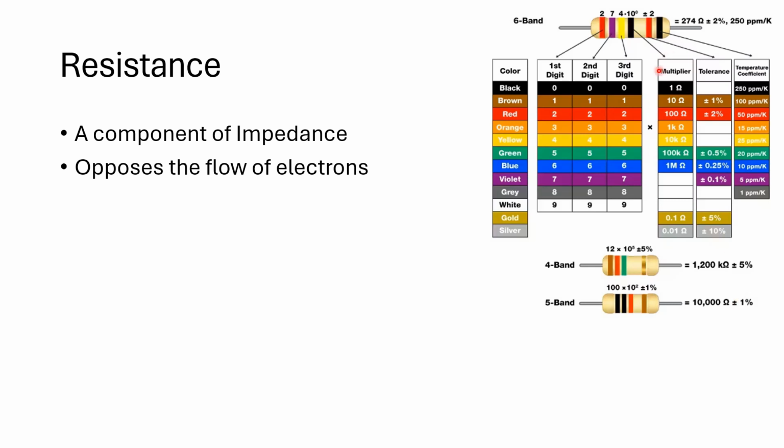You'll see these at the end of a CAN bus. They're called a terminating resistor. Their value is 120 ohms, and normally they're a 10%. So 10% of 120 is 12. So it could be 12 ohms higher or 12 ohms lower. Doesn't really matter for the terminating resistor of a CAN bus. So 10% in our case is just fine.